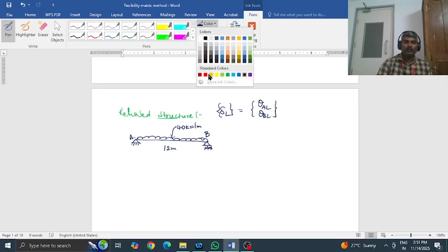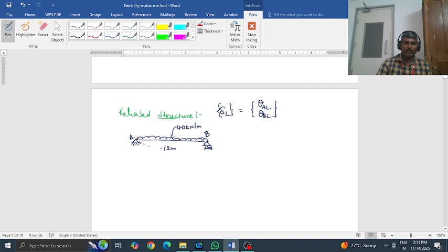So this beam due to the loads will bend like this, simply supported beam. So this rotation of point A is clockwise, and for the value of theta A, from your earlier study you know that for a simply supported beam with UDL, the slope at one end is WL cube by 24 EI. Same at the other end also, theta B, because of symmetry this also is the same. So I name it as L, suffix L.